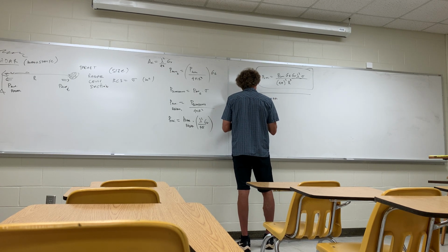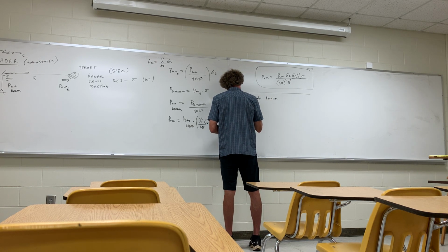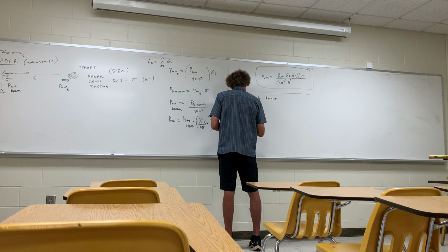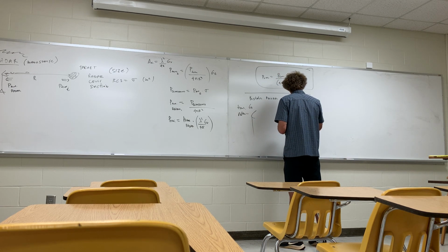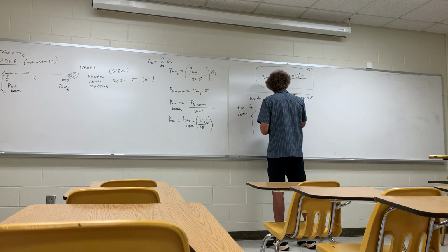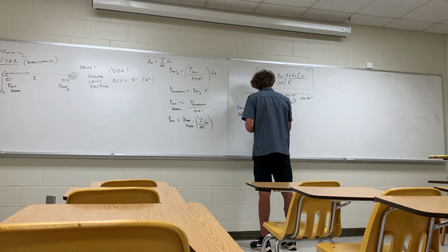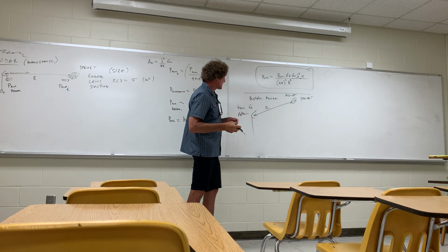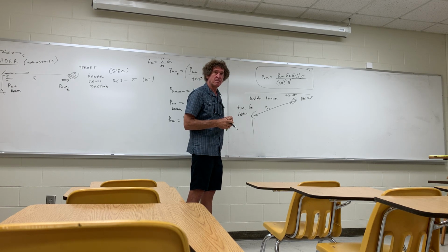You'll see the parallels. For bistatic radar, you're going to have a transmitting antenna. And it's going to have a gain of the transmitter. And there's a target out here. And the target has some sigma, which is the RCS. And this is going to be a range R1. So between the transmitting antenna and the target, we're assuming a range R1. Do y'all follow me?